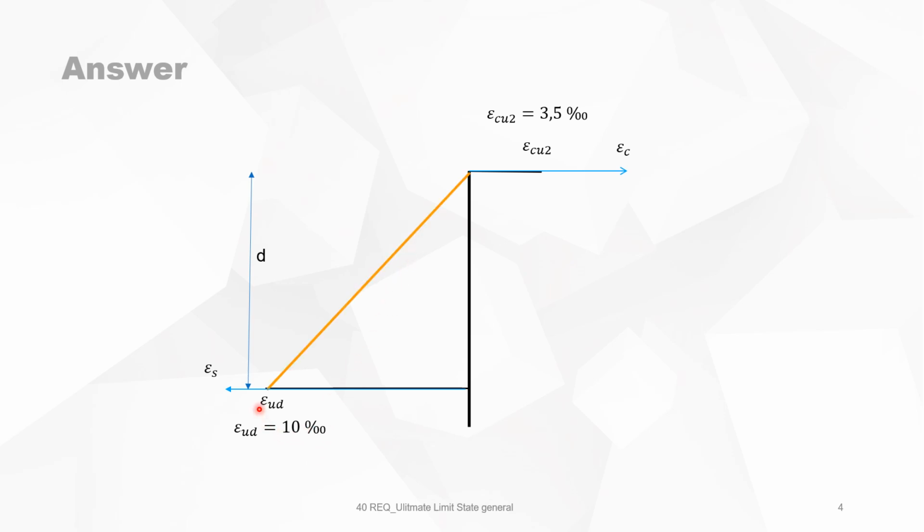Now, we are looking up all the regions where simple bending occurs. Well, it starts here. If you have a strain diagram going to the left, then you do not have any compression in the concrete, so it cannot be simple bending. So that's the first. Then, of course, this is also simple bending with the compression height. And this is the other limit for simple bending, because the region coming after it to the right, which is region 2b, is not possible, because then you need a normal force to make the equilibrium. So we have region 1b, 2a. Those are the two regions with simple bending.